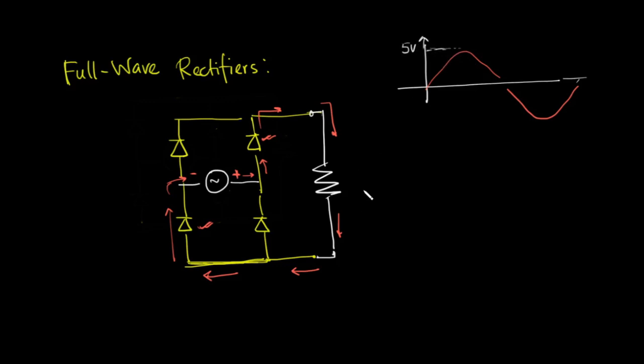So what will be the peak voltage of the output? Since 2 diodes are turning on now, not one, these 2 diodes will consume the equal of 2 diode drops from the input voltage. These 2 diodes will consume 2 times 0.7 equals 1.4 volt.